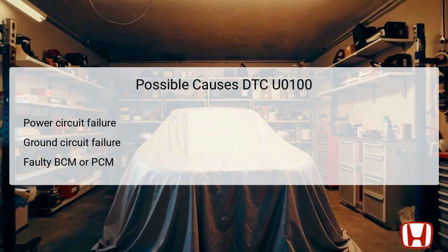When diagnosing this issue, it's imperative to check the integrity of both the power and ground circuits before proceeding to inspect the modules themselves, as these underlying issues often serve as the root cause of DTCs relating to lost communications.